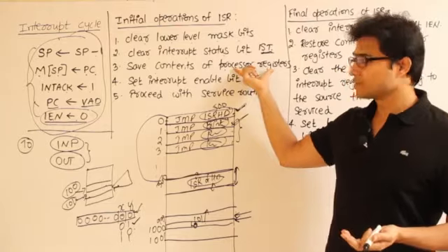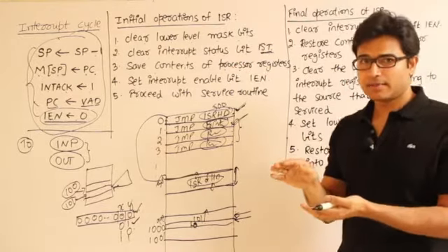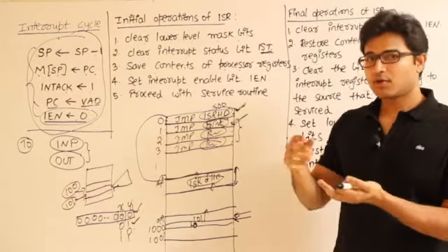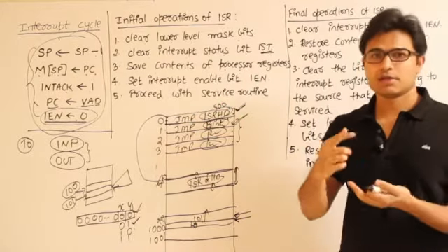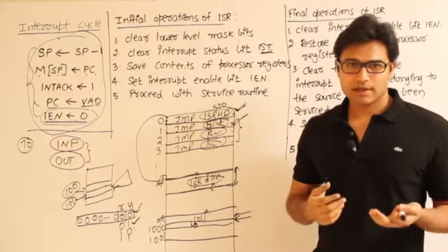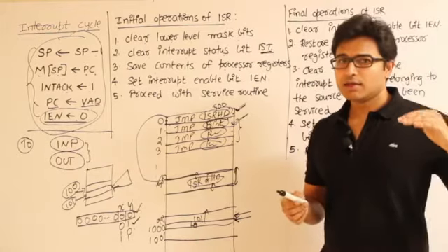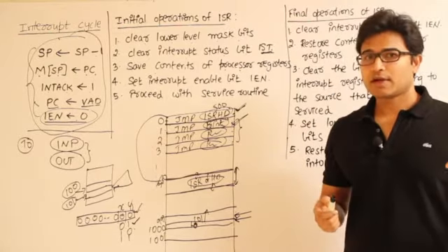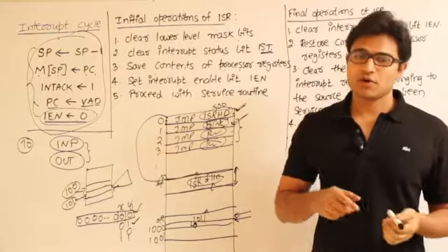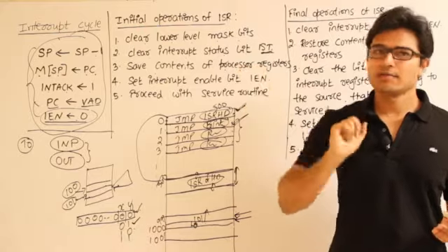So I think you know what this is. It is the context of the processor. So if the processor is executing a program, whatever is present in the registers has to be saved at some point, right? And later when the program resumes at that particular point, you have to load the registers with those values, so that there will be no ambiguity. Otherwise, if you don't store and restore the registers, there will be ambiguity, because the program which is currently executing might think that the registers are not modified, and it will try to use the values in the registers which have been modified by the interrupt service routines. That is why we are supposed to save them somewhere and get them back, right?